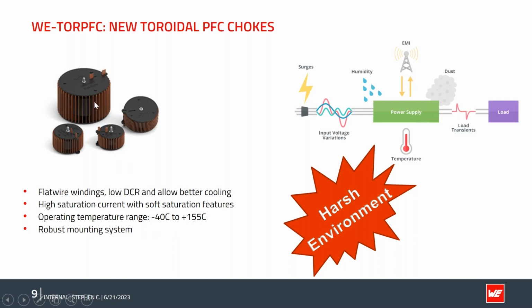And we also designed a robust mounting system by ourselves. As you can see, there's a plastic base plate and a cover, which help this series to pass the AEC-Q200 vibration test, which is, in the market nowadays, always required as a reliability test for high power products.